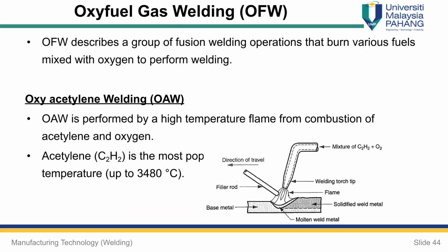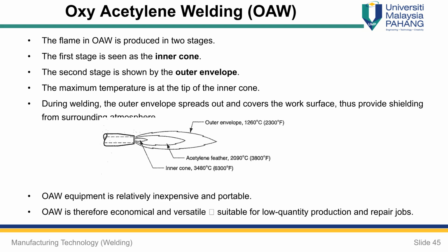Resistance spot welding, RSW, achieves fusion at one location of a lap joint using opposing electrodes. RSW is used for joining sheet metal parts using a series of spot welds with various electrode shapes. RSW machines include rocker arm spot welders, press-type spot welders for larger work, and portable spot welding guns for large, heavy parts that are difficult to move.